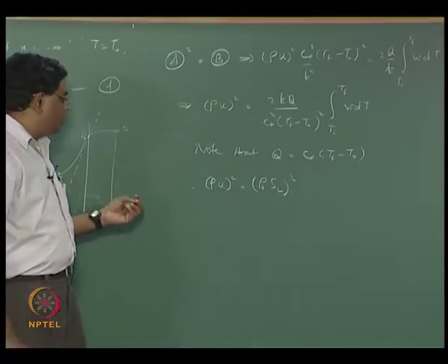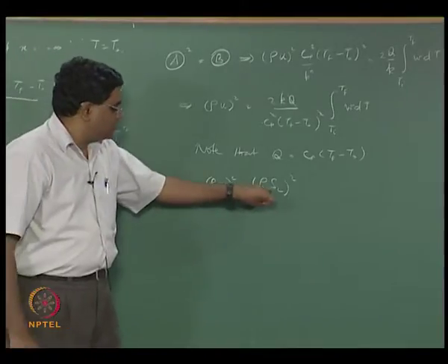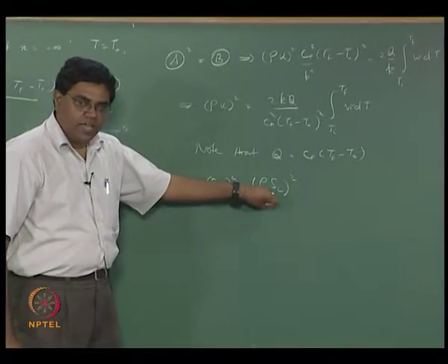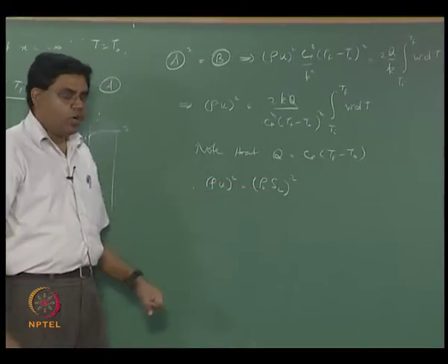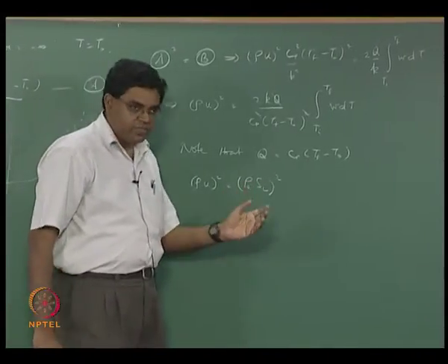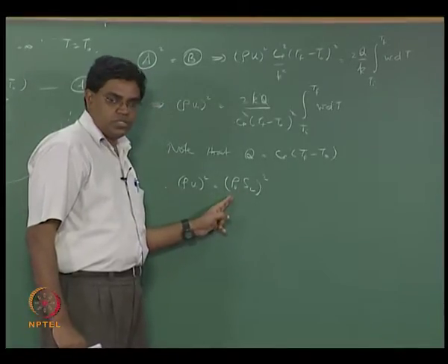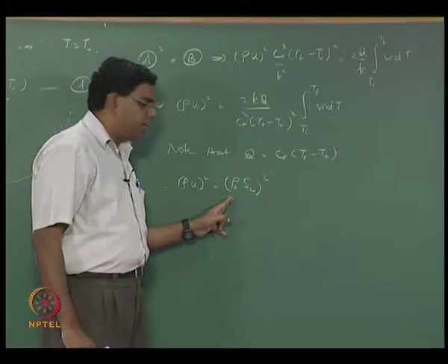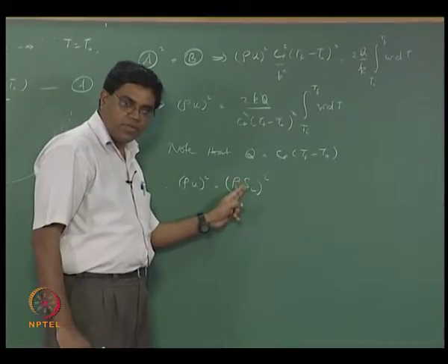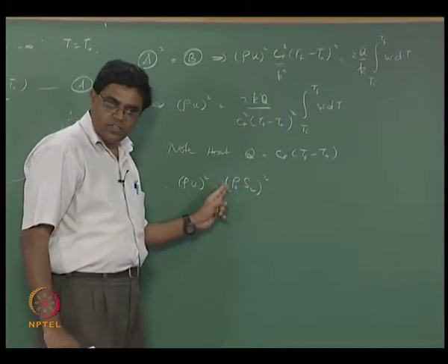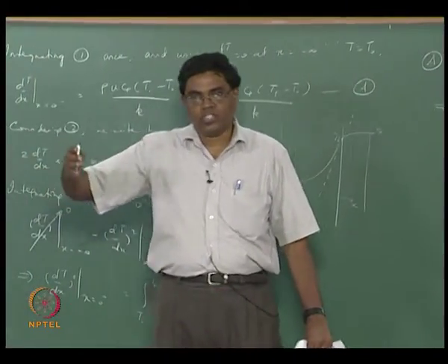Alright, so the reason why we are saying so many things is the way we want to actually look at this as the laminar flame speed. Okay, SL stands for the laminar flame speed. I shouldn't say always, but we have to specify this: the laminar flame speed is relative to the unburnt reactants. When you now say rho naught SL, that means the laminar flame speed is relative to the unburnt reactants. That means to say you now have a flame that is propagating into the reactants, and the question is,